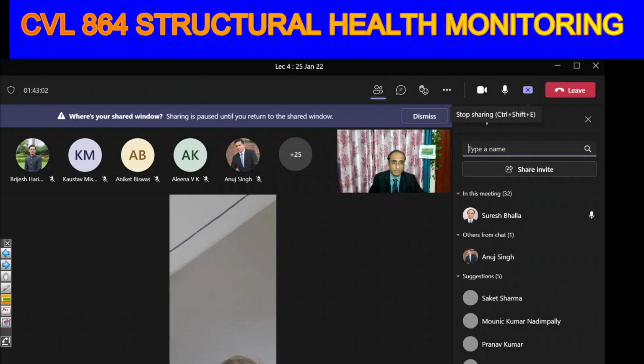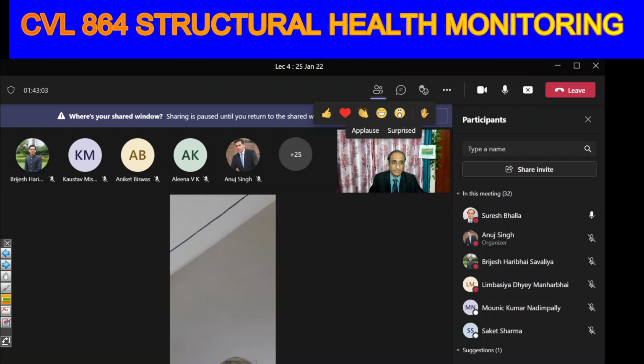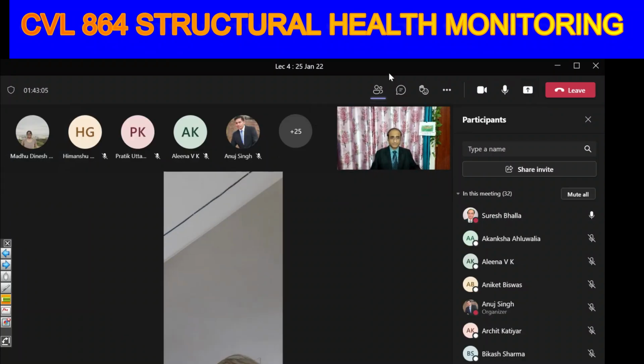So the FRF is independent of the position we are using for forming the FRF? For a particular position, we are measuring response and the applied force, right? And we are just varying the frequency. So if we change the location of input and output, the FRF will be the same? No, it will be different. It is very much point specific. So the FRF we are using is for a specific location. Exactly. The frequency response function has to be defined for a specific set of locations I and j. That's why we are using Hij, that is, we are dividing the response at the ith location by the force applied at the jth location.